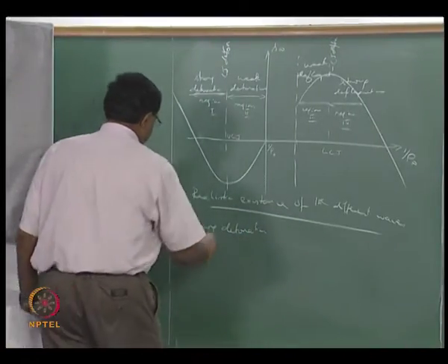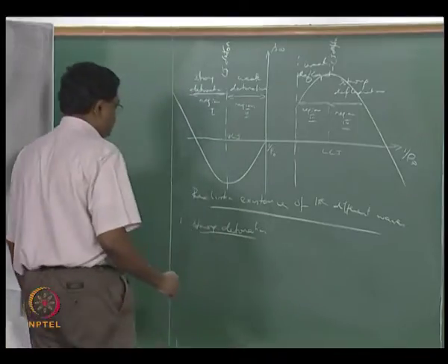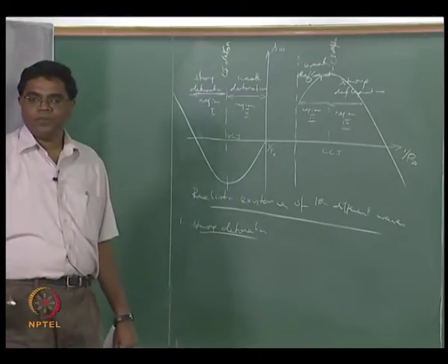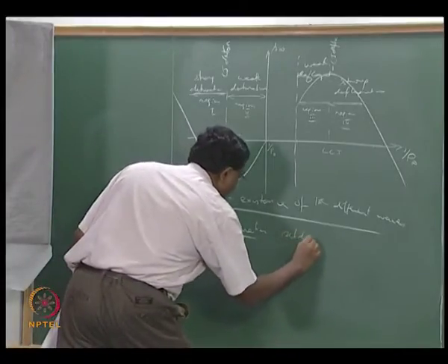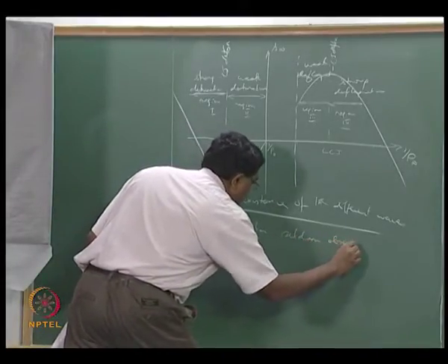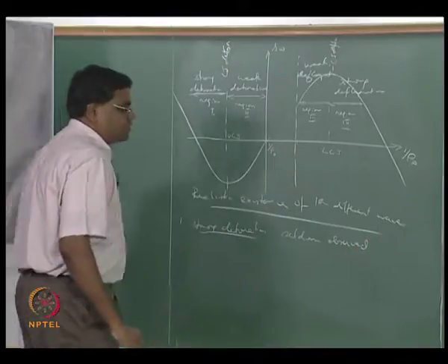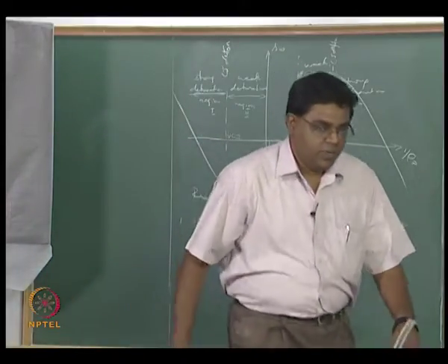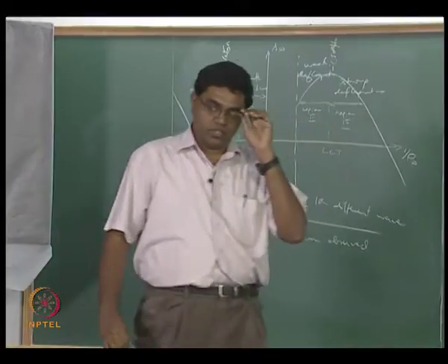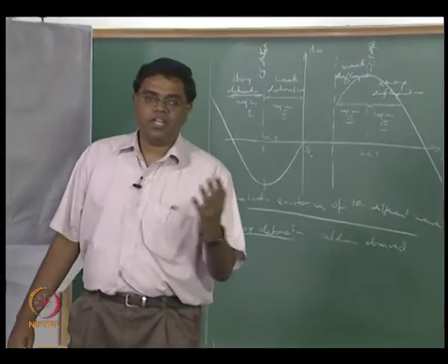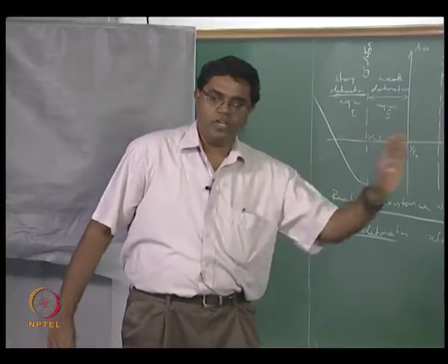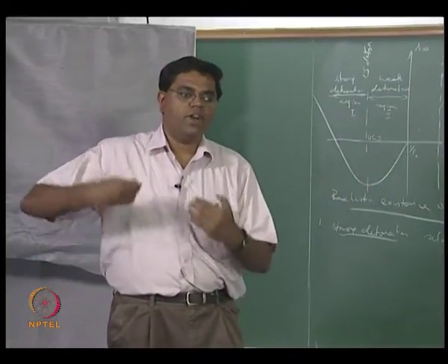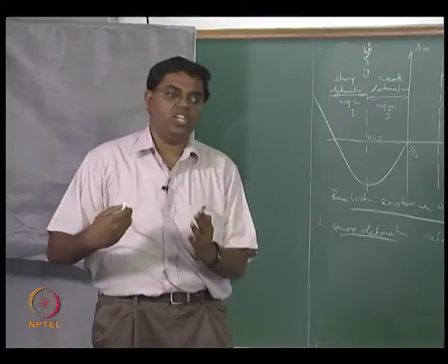What you will find is strong detonations are not very easily observed. Okay, so seldom observed, and why so? Because it's a strong detonation. That means you have to have a large compression, and you have to make sure that the gases are decelerated down to subsonic speeds from a supersonically propagating wave, and you have to have large pressures there and maintained.